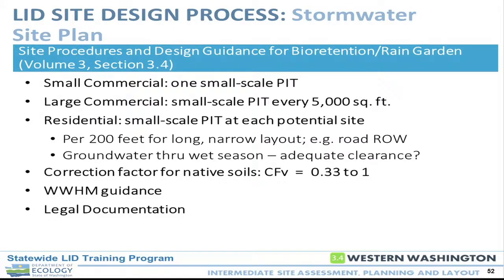But you also do need to monitor the groundwater through the wet season to evaluate whether you have adequate clearance to that groundwater layer. There's guidance in the manuals for the correction factors, everywhere from cutting your tested infiltration rate to 1/3 to no correction factors. And then there's guidance in there for WWHM and legal documentation.